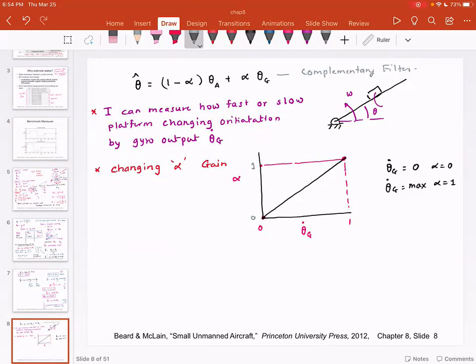So if we base all speed related measurement off our gyro output, yes, but there is a problem, because your gyro is never gonna give you 0. If you look at the gyro output, it's always going to be varying about 0. And on top of it, gyros have something called startup bias, which means when you power them on, sometimes they will start at 10-degree bias, sometimes they will start at 0-degree bias, sometimes they will start at 120-degree bias. So you have something called startup bias.